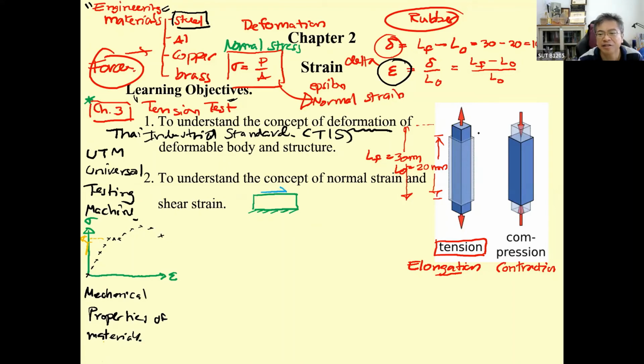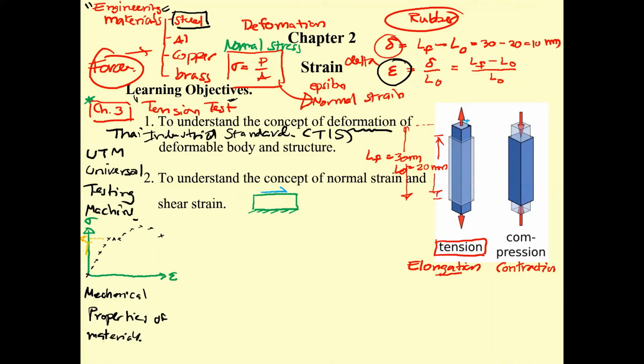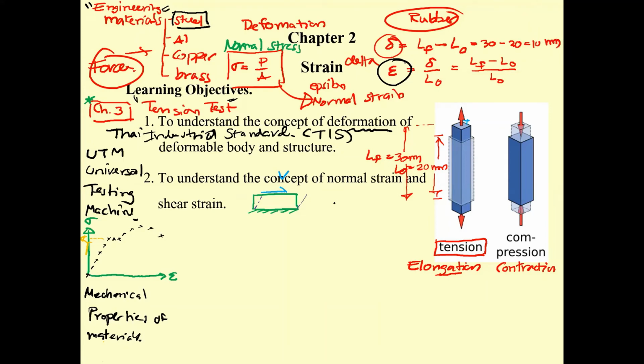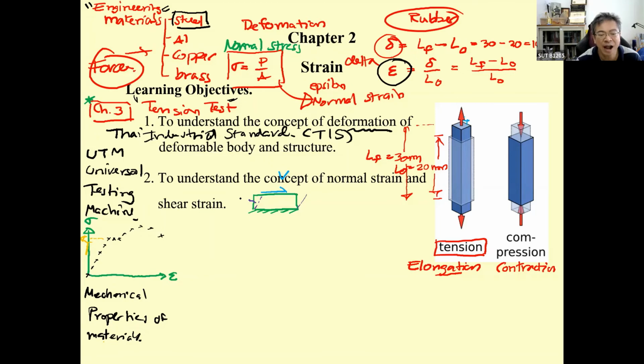The shear force is different from this one. This is the normal force. This is going to be the shear force. And when you apply this shear force, this one will change shape like this. And then we define the angle over here as the shear strain.